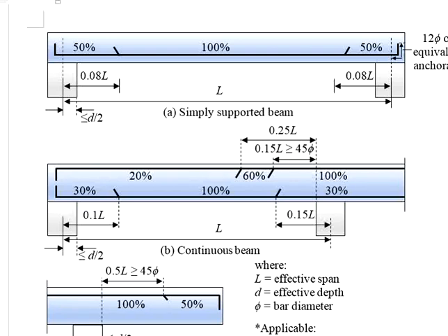However, due to practical considerations, you will require at least 2T12, even though no compression reinforcement is required in the beam. Now in this case, if the internal support requires 2T12 and the minimum required amount of reinforcement bar is also 2T12, there shouldn't be any reductions.